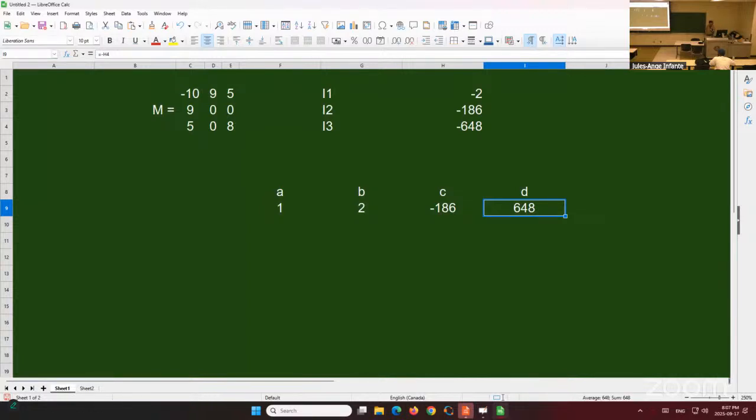And these are the parameters of the derivative. So the derivative of this term is 3 sigma squared minus 2 I1 sigma plus I2. So this is the quadratic with a, b, and c. So this is the cubic, this is the quadratic. And so the coefficient is 3, minus 2 times I1, and that's I2.